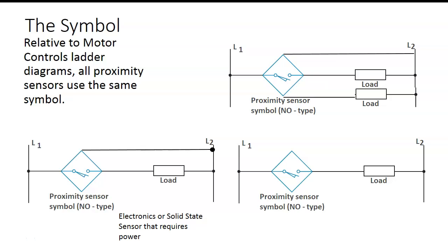Then we have a 3-wire sensor. These are powered themselves. The 2-wire drop would be especially problematic for lower voltage applications like PLCs. Most programmable logic controllers now currently power up on 24 volts, and I can't afford to lose 4 volts in a sensor, right?